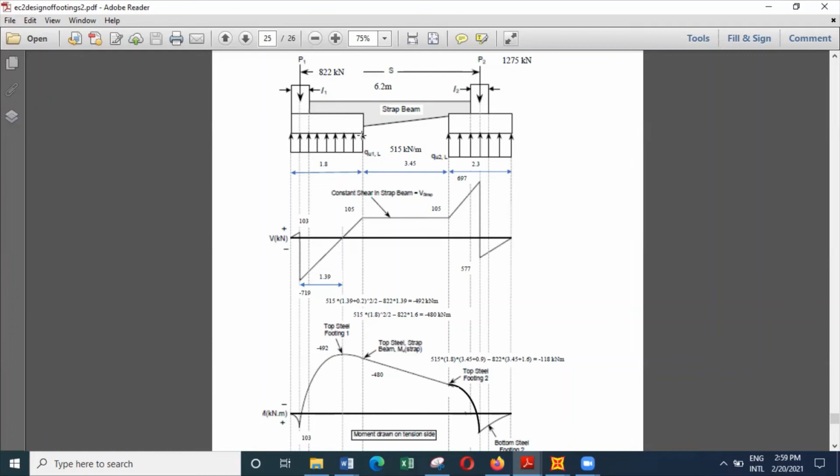And because the width of the base is 2.5 meters, again you can concentrate most of this reinforcement close to the column. We discussed it last time. We said the column plus 3D rule. So we can have a concentration of reinforcement close to the column as well. So if you consider the footing, you have to consider the direct shear failure in the width direction, not the length direction, because width is more than the length.